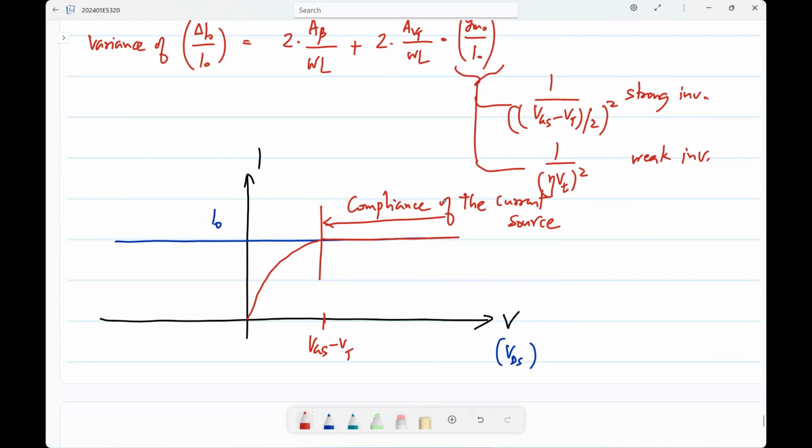Only thing is the mismatch has to be represented by appropriate sources. That is also easy. It basically depends on the nominal values of the currents and voltages and some mismatch related quantities. And then you need to know the variance of the mismatch of the component that you get from the process constant and the dimensions. Any questions here?